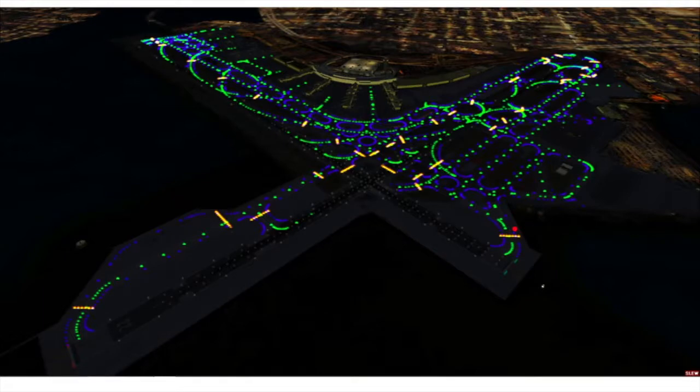The runway guard lights are meant to draw attention to the hold short line, the area where a taxiway meets the runway. You can see that this hold short line extends to both sides, though it's not that clear. You can also see that on those two sides of the taxiway, there are two yellow lights that are flashing.